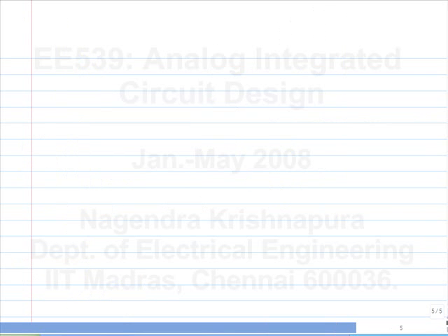Then you can also examine the magnitude response as well as the time domain response. One thing we can also try and figure out is what happens when P2 is very large, but we don't neglect it. Where will the poles be? No, poles again of the closed loop response. Both are real, that's correct. But what will be the values of the poles?